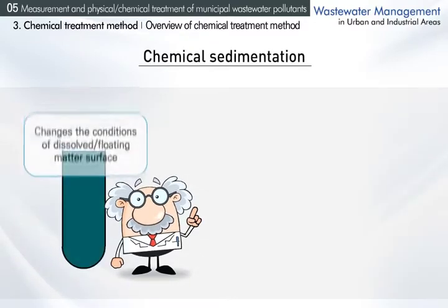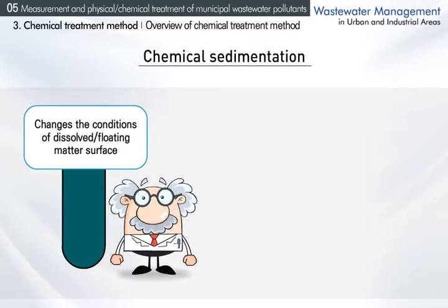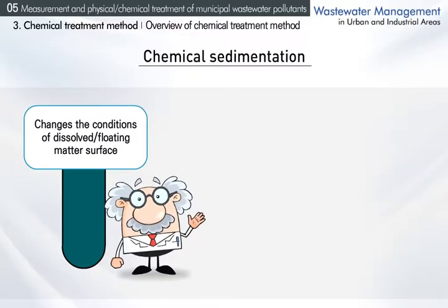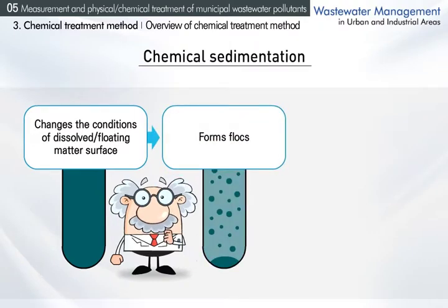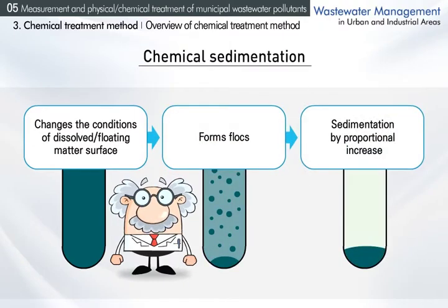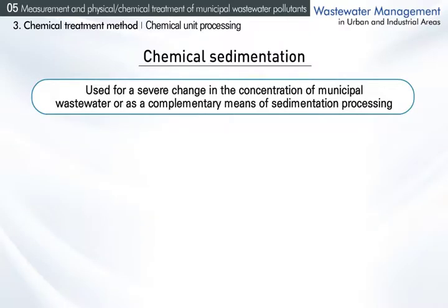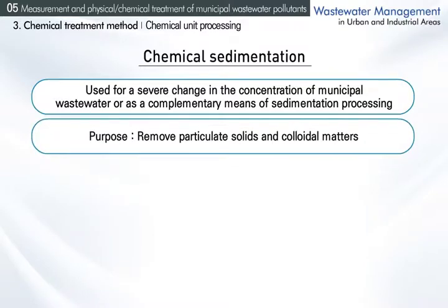This method changes the surface of dissolved and floating matters, causing the matters to contact and combine with each other to form floc, which grows in proportion and sinks due to sedimentation by gravity. It has been used when the concentration of municipal wastewater changes severely or as a complementary means of sedimentation processing, and mainly aims to eliminate particulate solids and colloidal matters.